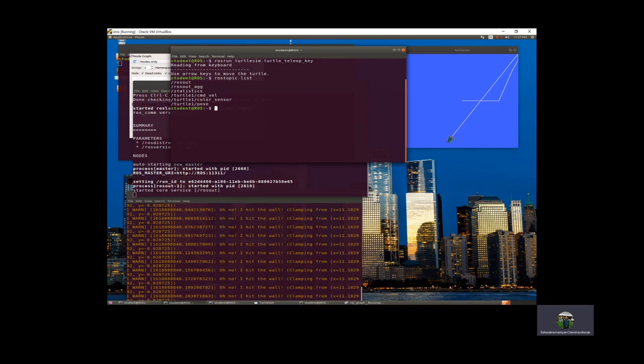Okay, you also have the pose information. So it'll give you information about that particular topic. You can always query that particular topic and get more information about it. Now, you can also use commands like rostopic echo. This will basically give you information about that particular topic. For example, if you just type this, it'll give you an error because you need to specify the topic. So you can give any topic name that you want.